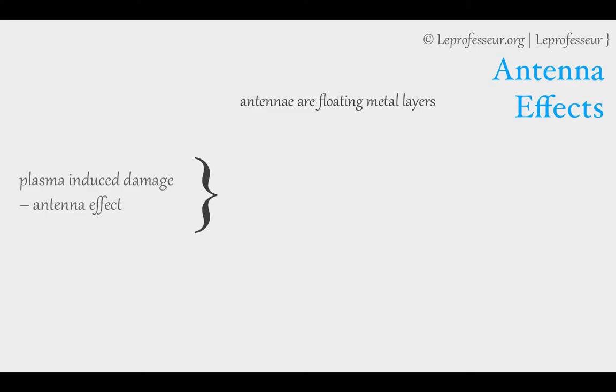Those who have been designing or writing code for digital design circuits in Verilog or VHDL might have noticed that if you don't connect the output or input of a block, electronic design automation tools give you the warning that this pin is hanging. That precisely is the warning for the antenna.